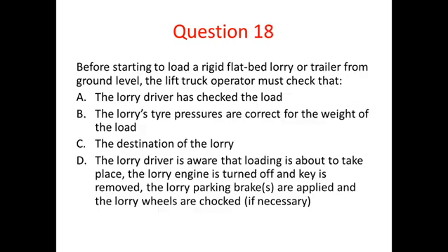Before starting to load a rigid flatbed, lorry or a trailer from ground level, the lift truck operator must check what? Well, you need to check a lot of things. You need to make sure that the lorry driver is aware that loading is about to take place. You need to check that the lorry engine is turned off, the keys are removed, and then the lorry parking brakes are applied and the lorry wheels are chocked, if necessary, of course. So ultimately you need to make sure everything's safe before you go about performing a lift.